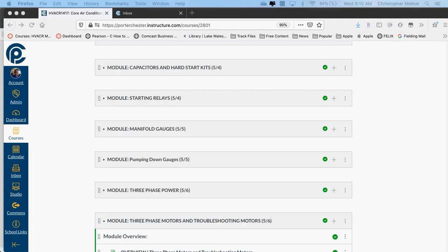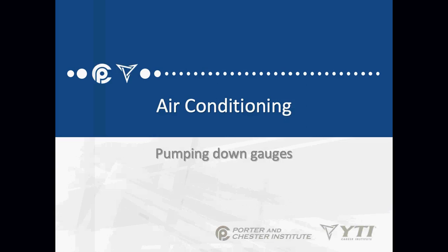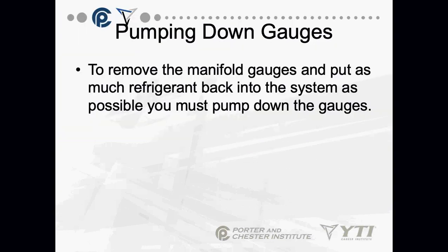Okay. Let's talk about pumping down gauges. Does anybody know what I mean when we talk about pumping down gauges? Can anybody who's maybe had refrigeration before give me a brief synopsis? What we mean is, we have to be able to remove our refrigerant gauges once they're installed on a system. We have to be able to remove them without losing refrigerant back into the environment.